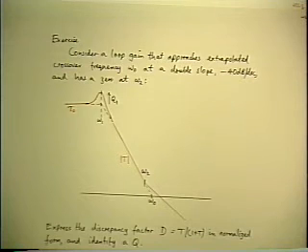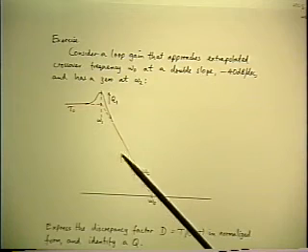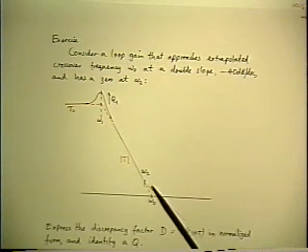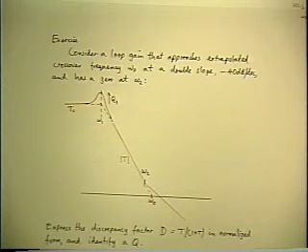So what you have to do is to put a zero in. In fact, I already mentioned this in the progression of how you design a loop gain in order to fill in that window appropriately. Since we already have two poles, you have to put one zero in order to flare out the response and bring the phase lag back down before you get to crossover. So there's an analogous problem now. Where do you put the zero in order to get an acceptable closed loop response for your switching regulator?